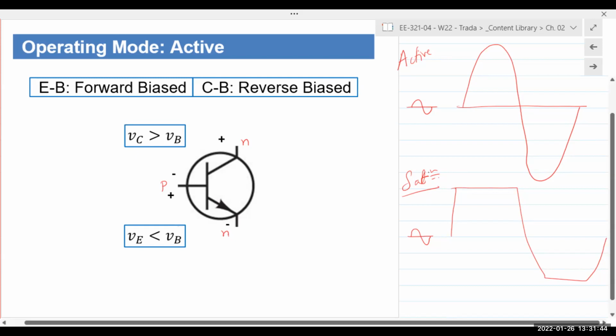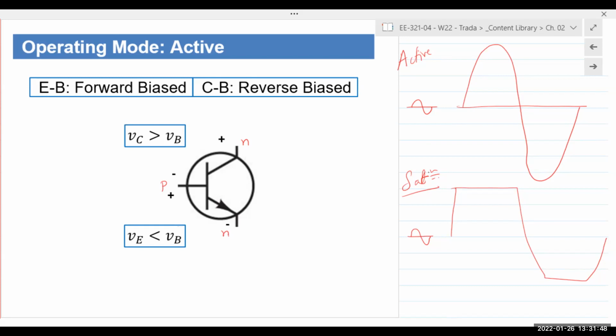So that goes back to the question that was asked earlier. What does saturation actually mean? Well, the transistor is completely saturated, and so it just means that all the charge carriers are just flowing through the junctions because of forward bias, and you have maximum current coming out of the output. And so instead of the output actually being the signal that we want, it is basically distortion.